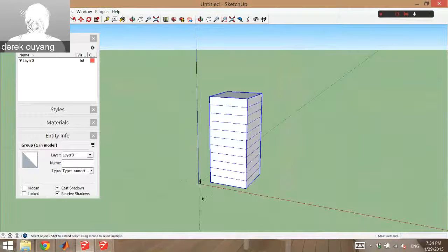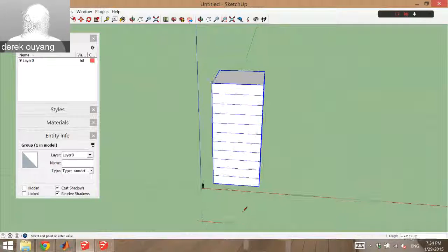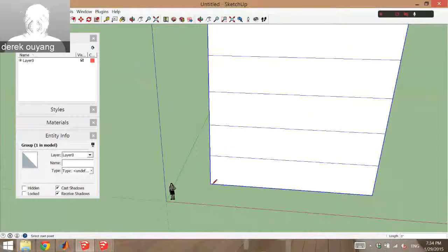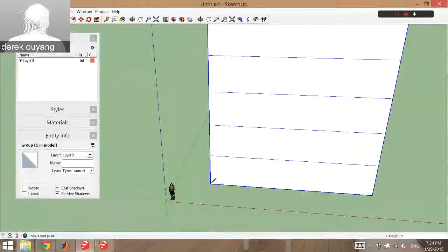Then you can take advantage of the fact that, remember, we have those locking axes, right? So we can do red, green, and blue. You can use blue and red in this case to get from this corner, and let's say this corner of the lateral frame is going to be your origin in MASTAN. Then you have to put very little thought at all into it: my first node is here, and then it just tells me it's 10 feet, 120 inches, and then my next node's here.